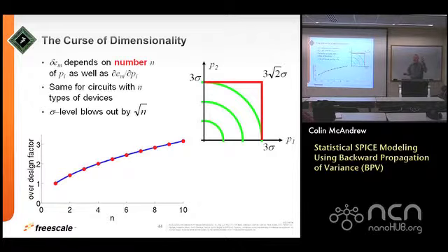But if I do the same thing for PMOS, and then if I've got resistors and capacitors and bipolars that my circuit is sensitive to, and I've got 3 sigma files for each of those things, if I then put in worst case models for each of those components, I continually blow out the amount of variation that I'm putting in, and really over-design the circuits. Over-design is good, particularly when you provide to automotive who are very sensitive to it, but it's very bad when you're competing with someone who has better design practices and can make smaller die that use less power. So this is, again, something that people don't typically know.